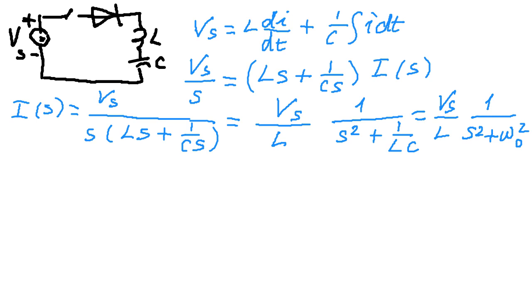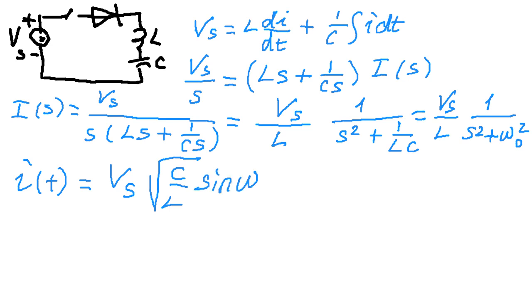So the inverse Laplace of this one is a sinusoidal function, which is equal to i(t) is equal to Vs times square root of C over L sine omega o t.